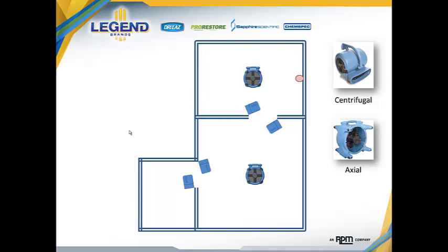And if I can get the same humidity at 1 meter above the floor as I'm getting right at the surface, then there's enough airflow. However, if I see a substantial deviation in the temperature and humidity 1 meter above the floor versus right at the floor surface, air is not moving fast enough to bring that moist air away from the surface and replace it with the drier air in the balance of the room.